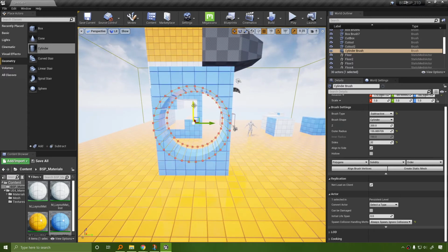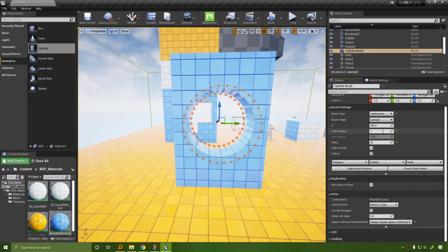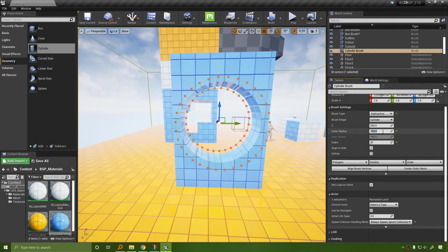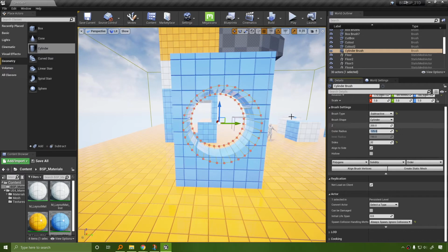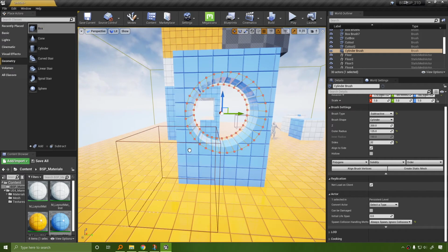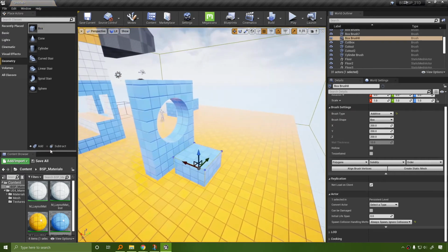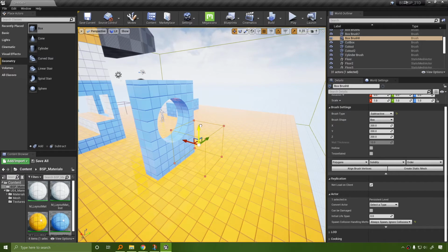I'm trying to make like an archway. Let's go ahead and mess with the outer radius so we get something a little bit thicker maybe. 150. 100. Might be too small. Okay, I might live with that. Move that up here. I'll grab box. Probably move that to subtractive immediately. And we'll move this up here, down with end.